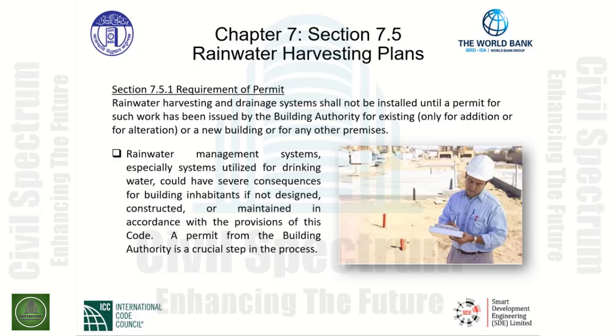The permit requirement will also require the applicant to submit construction documents for review and approval. Additionally, we're really concerned about the materials, the connection methods, where we are getting the rainwater from, and the treatment of rainwater before it is allowed to be reused for some purpose.